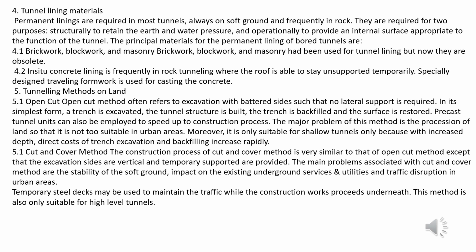Tunneling methods on land. Open cut method often refers to excavation with battered sides, where no lateral support is required. In its simplest form, a trench is excavated, the tunnel structure is built, the trench is backfilled, and the surface is restored. Precast tunnel units can also be employed to speed the construction process. The major problem of this method is precision of depth, and the direct cost of trench excavation and backfilling increases rapidly.